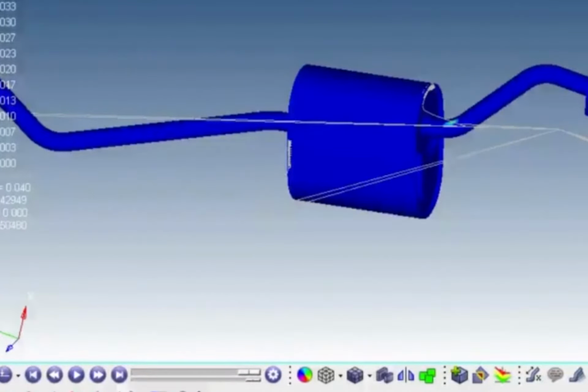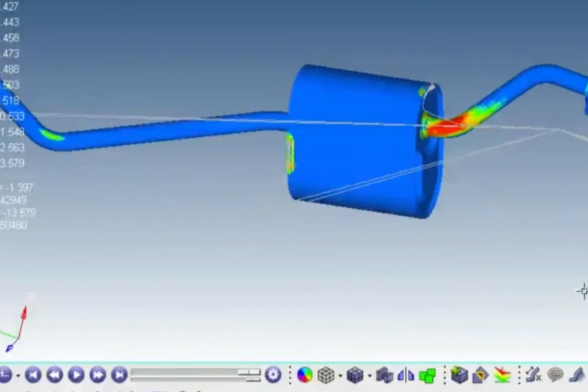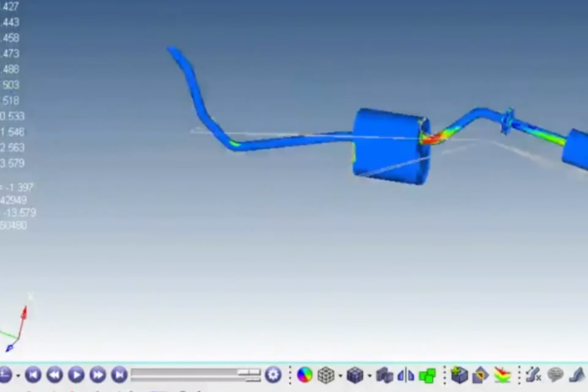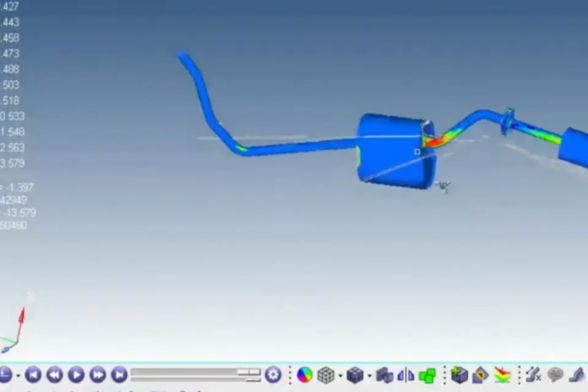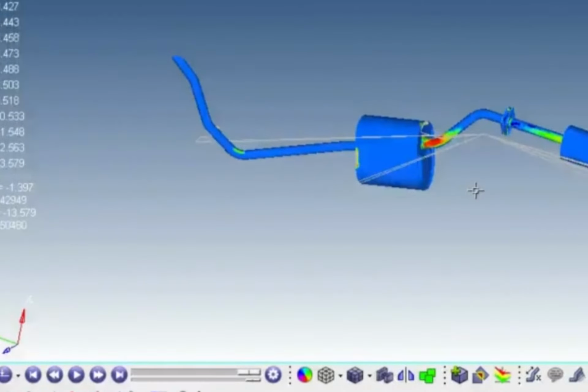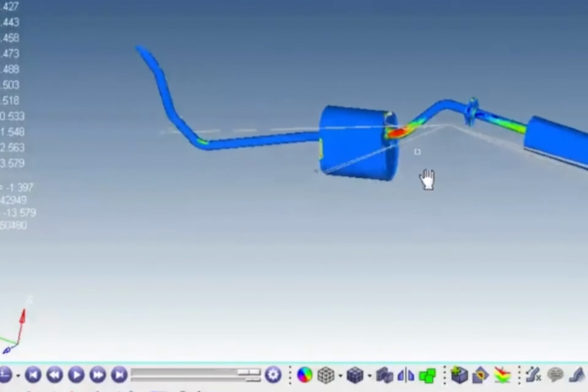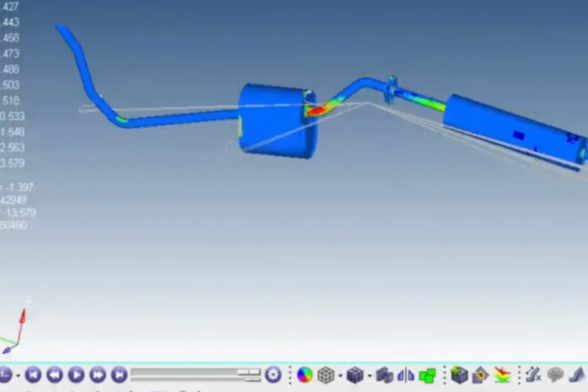But if you plot log of damage, it will spread the results more, so you get a nicer plot. I'm not sure it tells you a lot more, but it's typically what people do. They will typically show the result in terms of log of damage. Okay. We also have life, so you can do log of life, for example. That'll simply be the reciprocal of damage. So log of life, we have very low life corresponding to high damage in the same location.